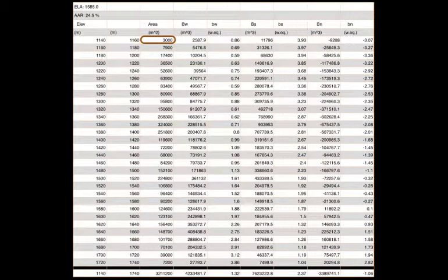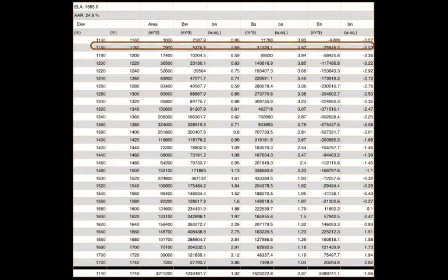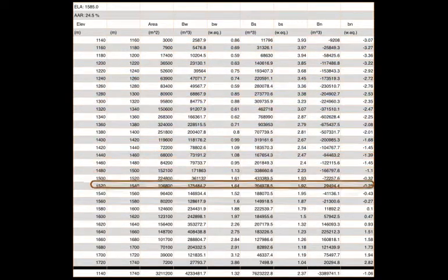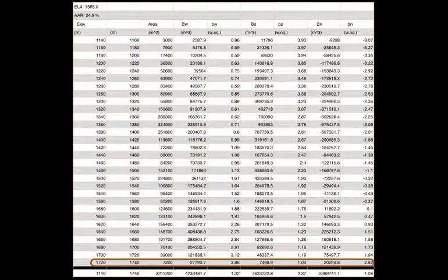The area of the glacier in this range, the volume of water accumulated in this range, accumulation in meters of water equivalent spread over this range, the volume of ablation, ablation in meters of water equivalent, net volume change, net meters of water equivalent. Then for each 20-meter band until the end into the head of the glacier. Finally, the sum of all these parts.